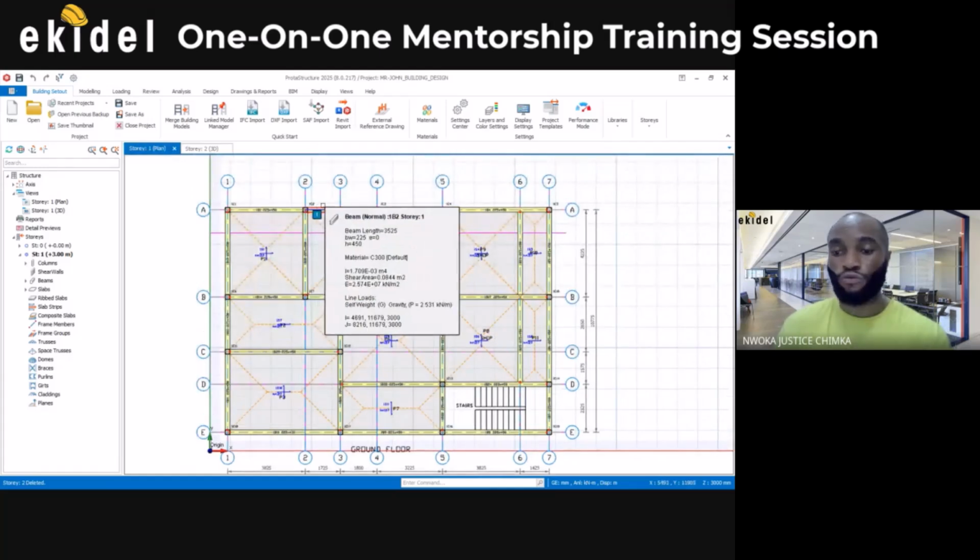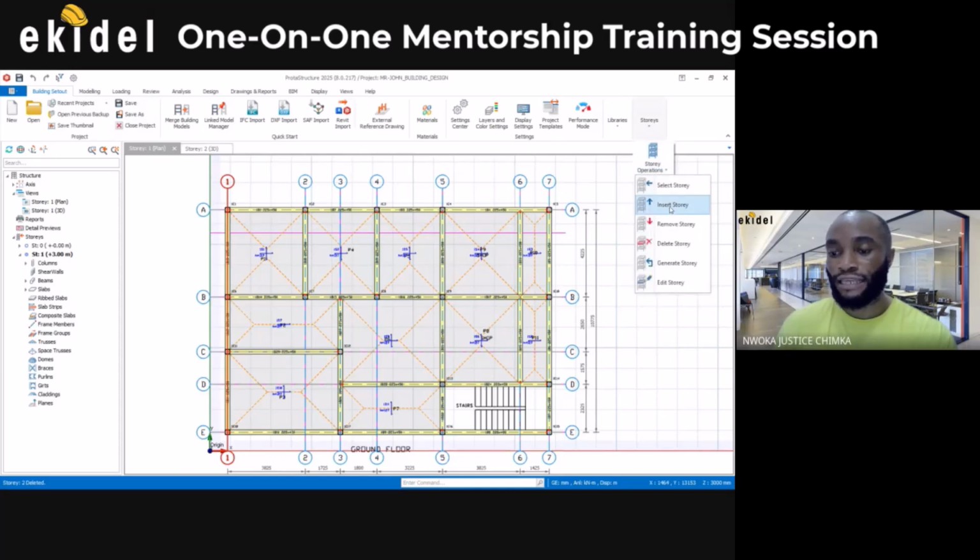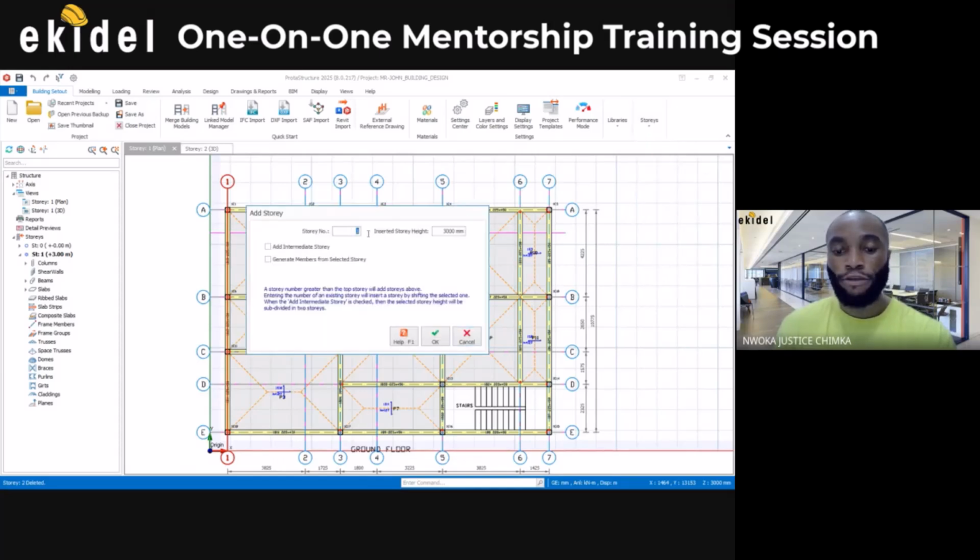To now insert a story, come to business setout here, come to stories here, story operation, and then insert. Then come here and type the number of stories. If you have up to 5 stories, just come here and put 5 or something. Understand? I'll come here now and type 2. But this is just one floor. Ground floor is seen as story 1. So the next floor is seen as story 2.